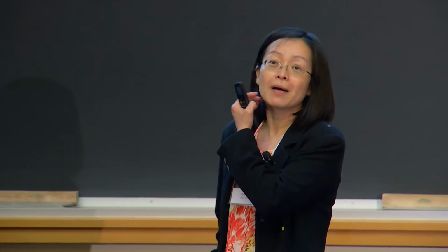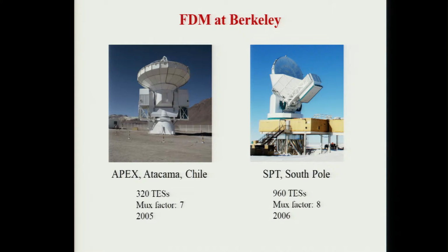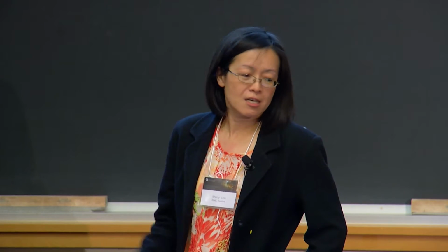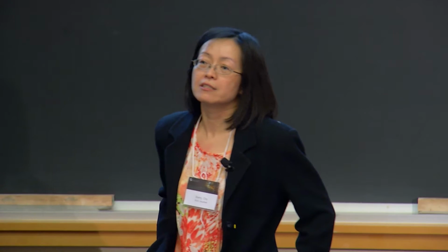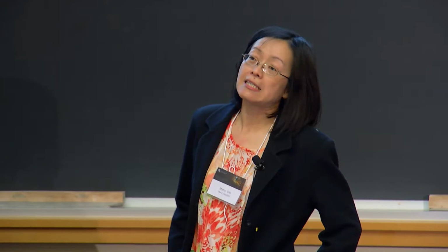So let me come back to FDM at Berkeley. That's what I did with John. And as I said, Chile was the first one. We deployed in 2005 for 320 TESs. And at that time, the mux factor, which means how many SQUID arrays we need per X detectors, for that first one we could only do 7. And soon after, a year later, the factor was 8.